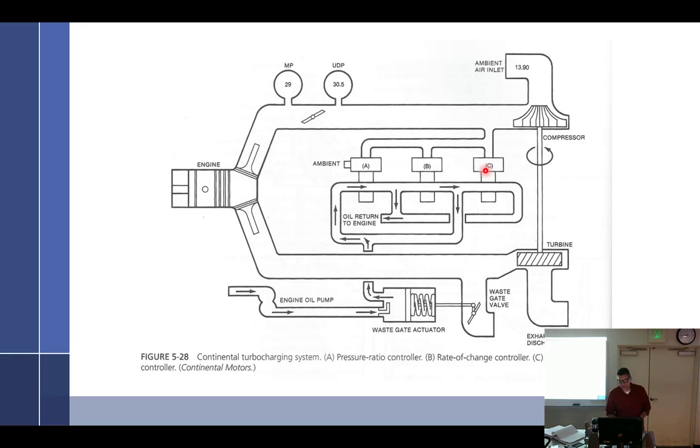Well, one of the problems with that is at some point 40 inches is a little excessive, because you have a differential between what is in the manifold and outside the manifold. And that's where they do it here with the Continental, is to watch that. If you have too much of a change, then you can kind of predict, well, that means we're compressing air at this rate, it's going to be this hot, it's not going to be what we want. So we don't want what's in the upper deck to exceed a certain difference, in inches of manifold pressure or mercury, PSI if you will, from what's outside of it. That made sense, I hope.